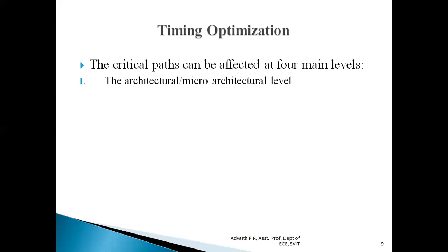The architecture of the chip should be as small as possible. This requires a broad knowledge of both the algorithms that implement the function and the technology which is being targeted, such as how many gate delays fit in a clock cycle, how quickly memories are accessed, and how long signals take to propagate along the wire. All these details will be analyzed in this level called the architectural level. There we have to identify the critical path and sort it out.